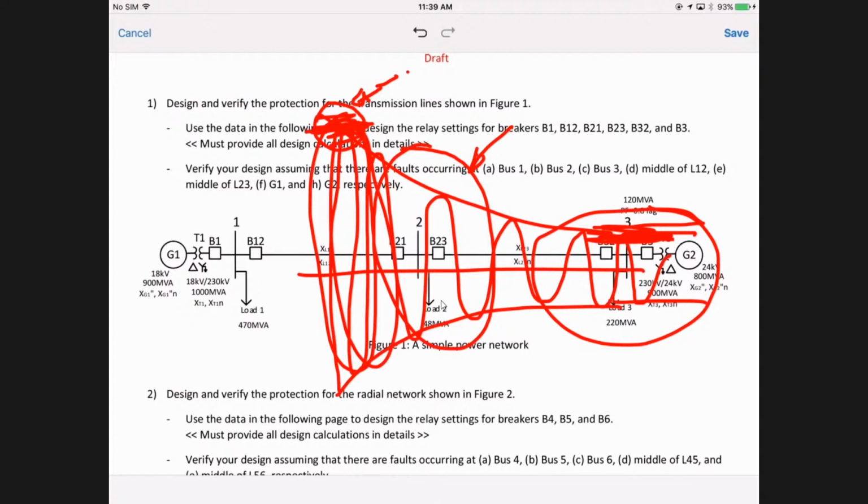The heat generated will break the insulation and make it worse and worse, and the heat is RI squared. So this is huge. The severity of the damage is squared. So the first cycle is very important. We have to protect it. If we don't protect in the first cycle, then there is no protection at all; it will burn out already. So that's why we use the subtransient reactance.